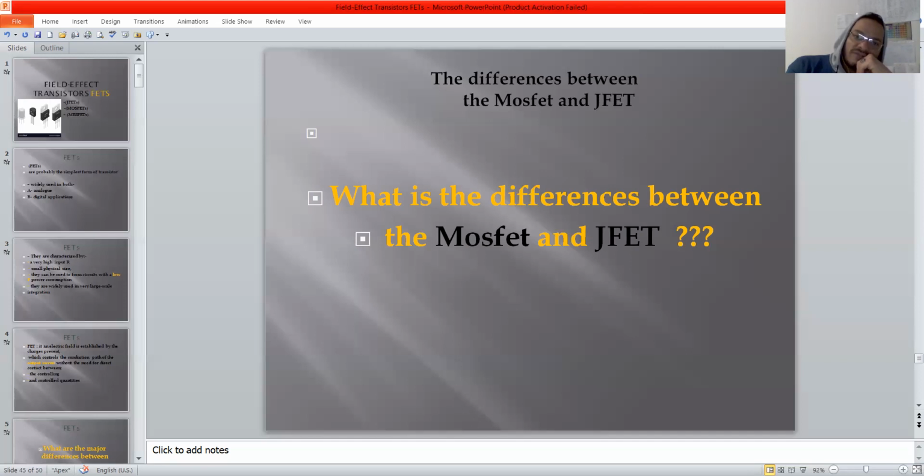The lower end of the same material is connected through an ohmic contact to a terminal referred to as source. The two P-type materials are connected together to the gate by using this wire to the gate. Now, in the absence of any applied potentials, what does absence mean? That means we don't have any applied potential.